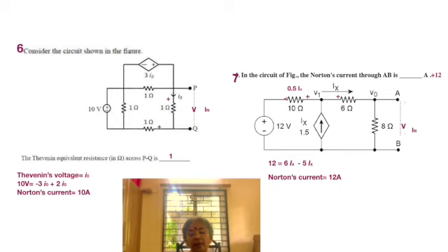If 1.5 Ix amperes moves upward, then towards the right Ix flows and the rest flows to the left, by Kirchhoff's current law. So we have 0.5 Ix going into the 12 volt source. The directions are shown, and the drops are shown accordingly. So now we have all the currents distributed.